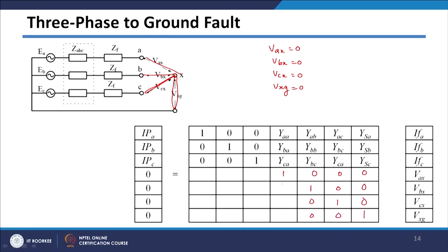So, for a particular fault we can get these remaining 4 equations, add them to this system of equations which is written in matrix form and then call this X, this is the QLLLG fault matrix and this is, say, Y. Then we can get the Y matrix which is unknown, which will be equal to QLLLG fault matrix, its inverse multiplied by X.